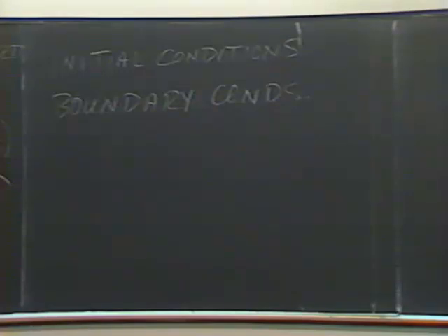And the way to do that is to use the same model to calculate the salinity concentration in an estuary, and assume that the salts are transported the same way that the sediments are transported. If you can reproduce the salinity by adjusting D, then you have at least some confidence that the dispersion coefficient is representative of the physical system.